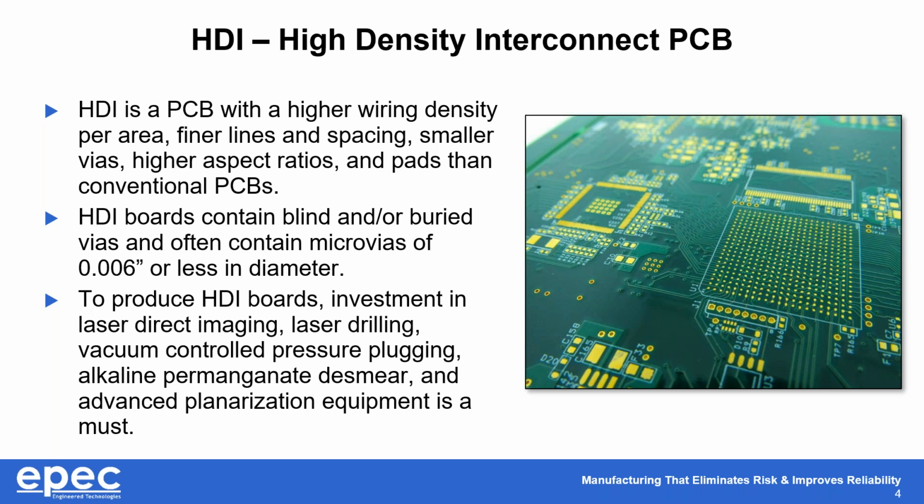And technically, if you look at it today, 5 years ago, if you were talking 6 mil lines and spaces, that was really high tech. And now you can get down to 3 mil lines and spaces, and that's really commonplace. So the business has changed dramatically.